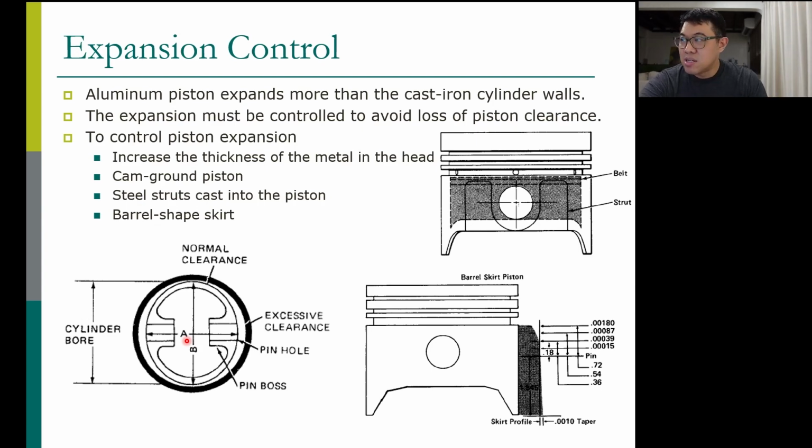You can also do the barrel shape. We know that the top is at a higher temperature than the bottom, so we taper it a little bit. We call it barrel shape, which means this part is smaller than this part, because this one is hotter. When it expands, it becomes the same, right?